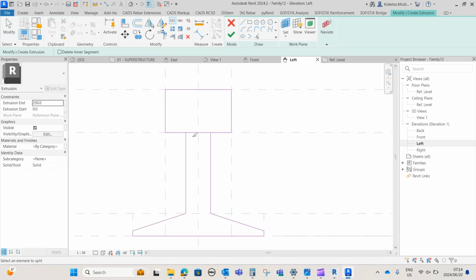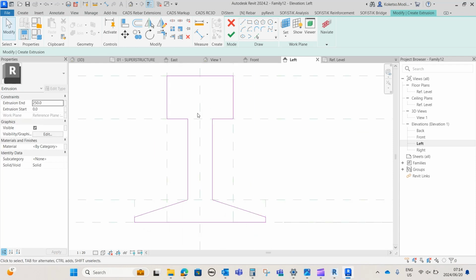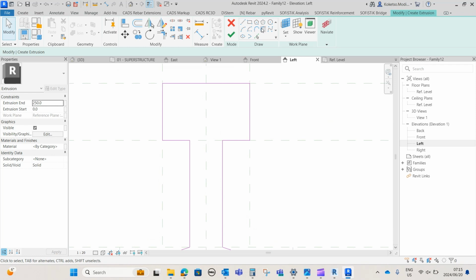So this is basically what we have so far. So you're gonna slice it and then remove this line. So we're gonna apply our radiuses. So you're gonna go to fillet arc and then say radius. So the first one, your radius, you're gonna set it to 11, and then you're going to select these two,